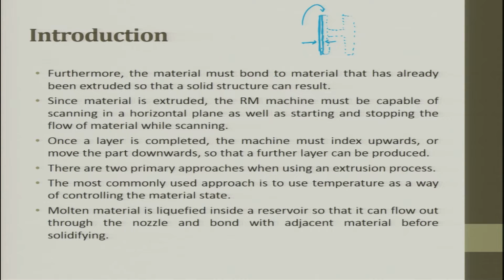It might give you a very poor look. So, this also should be kept in mind, that there should be an overlap, and there should be a sticking between the two roads. If I try to draw the cross section, it will be like this. There has to be something like this. This will make sure that there is a proper bond with the material that is already extruded. So, this is first and this is second. If this one dries off, then sticking will be a problem. So, you should make sure that this one does not dry, and when the next one joins, it should stick.